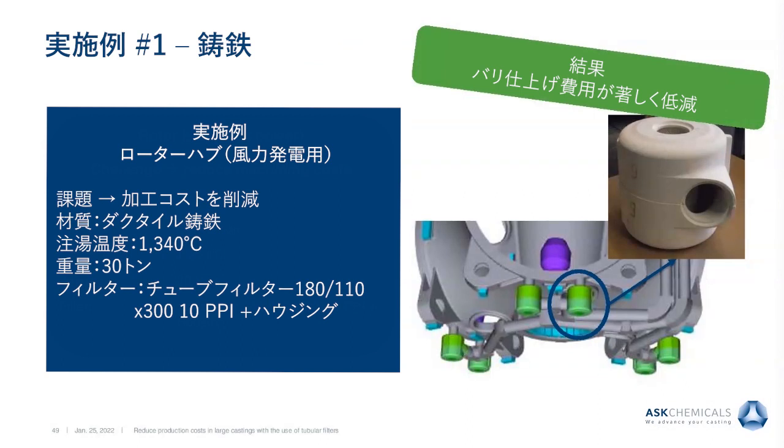Especially in the manufacturing of large castings, as I already explained, people must install big downspools and runners, and in many cases, multiple runners are used. This can promote the generation of turbulence and consequently the risk of reoxidation within the molten metal. At this point, an improved, more consistent and safer solution for filtration was needed. To implement it, we cast this one with 6 filters of the biggest size and also 6 housings. And the filtration was really, really successful in this case.